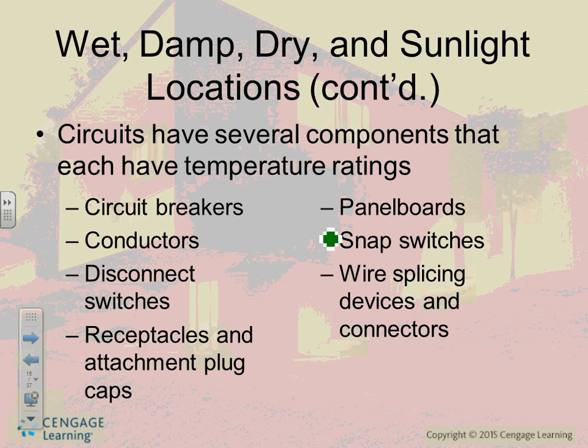XHHW-2. Now, if you don't know, can anybody tell me what XHHW-2 is? Find it, guys, and tell me two things. Is it wet location and dry location? You can tell just by looking at it. Okay, wet or dry. Another thing, what's the temperature rating for this one? 90. For what? 90? Yep, for dry or wet? Thank you. 90 for dry and wet.